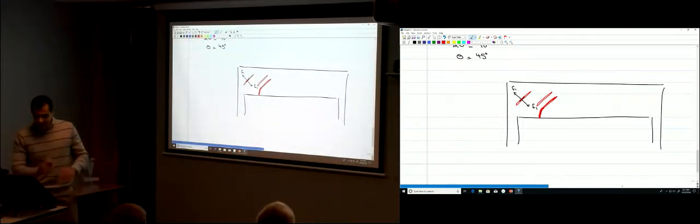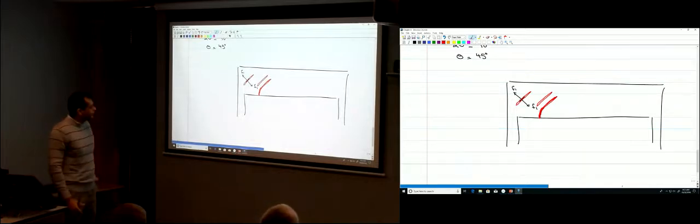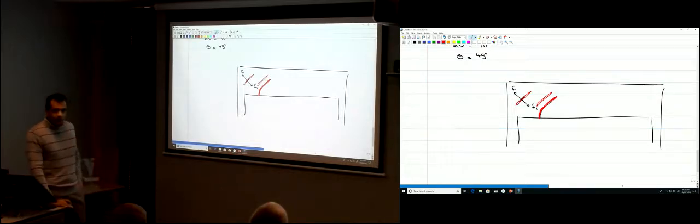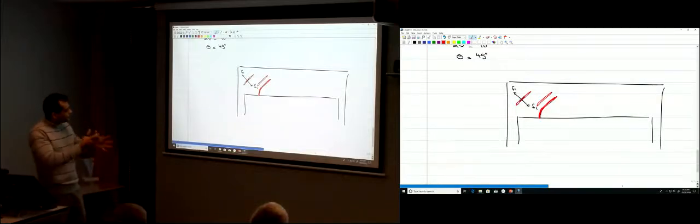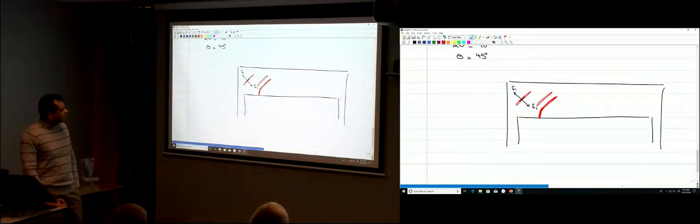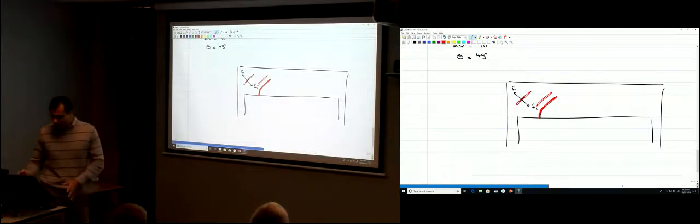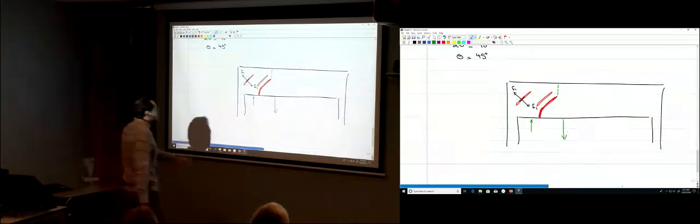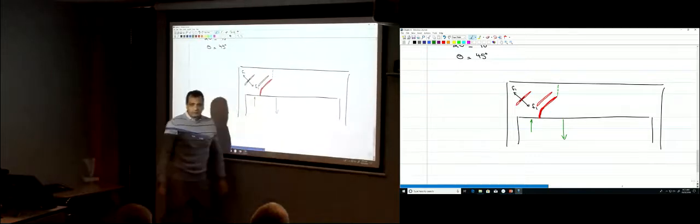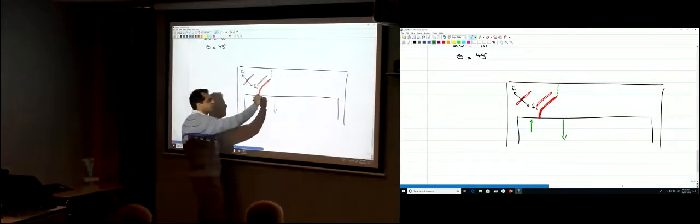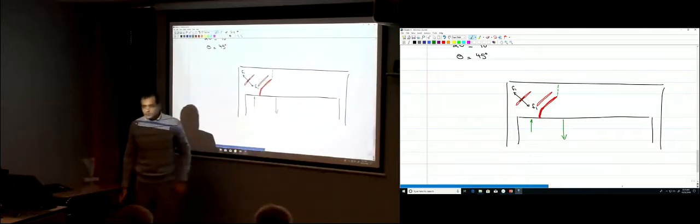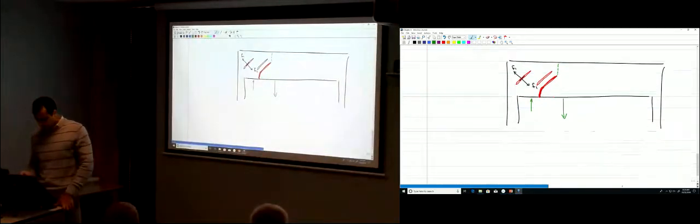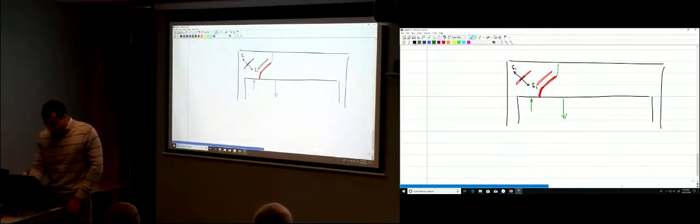So now you have this crack. There is a tensile force trying to open this crack. I have a shear force that is also applied on this crack. I want to resist it. The problem is now my beam is cracked like this. I'm afraid that it would fall down. This part goes up, this part goes down, and then it breaks due to the applied shear force on that crack. So the beam breaks into two parts. So actually it goes like this.